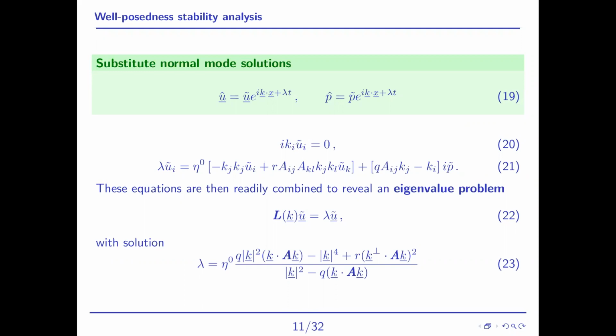Okay, so as I said, we've done the principal part, and that really helped us have a simple system. Substitute in our normal modes. We've got constant coefficient equations, so the normal modes are solutions there. You may be thinking, in normal stability analysis we've got to consider the boundary conditions as well. Again, because we're doing these high wave number modes, we're zoomed right in on the base flow. It doesn't matter how close you are to the boundary, you don't need to worry about those conditions. So these modes are always permissible in this kind of infinitely small scale limit.